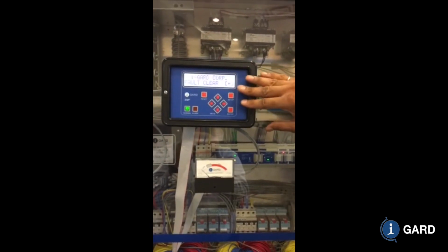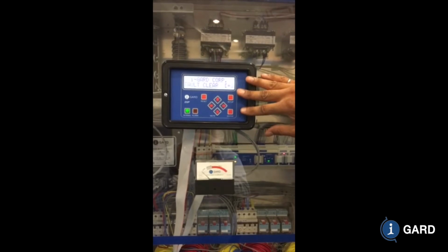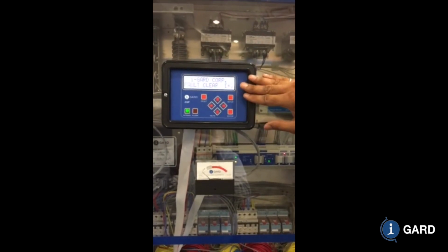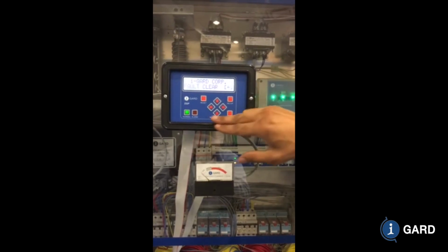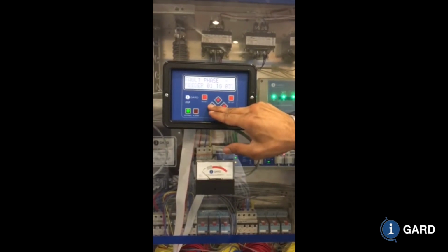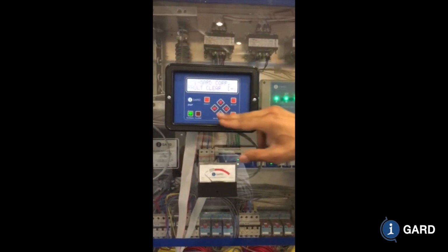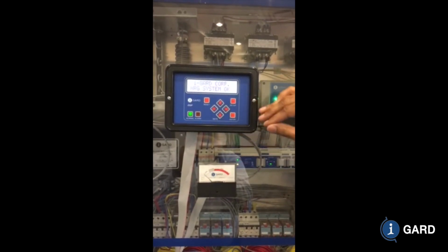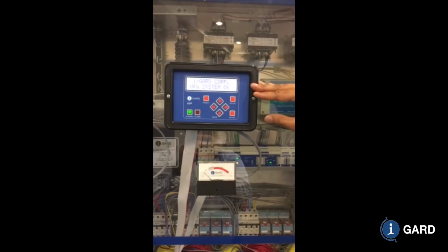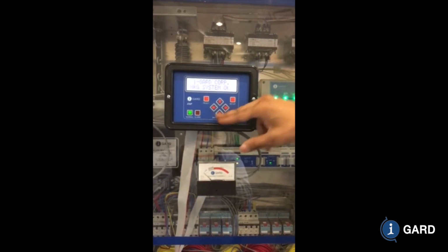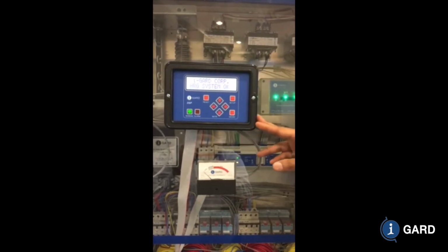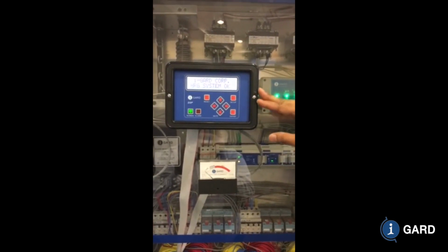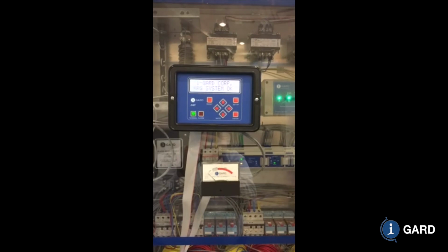Again, the DSP is self-resetting, so when the fault is cleared, you get this screen where it says fault clear. When you're at this screen, you can hit the left button and see what the last fault was. When you hit reset, it clears that memory unless you have a logging module. If you have a logging module, then you can hit the left button and scroll through the last 100 items. So that's just some of the screen pages and what you see when you're in an alarm.